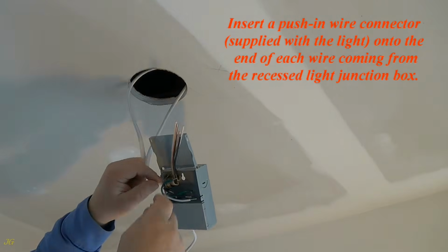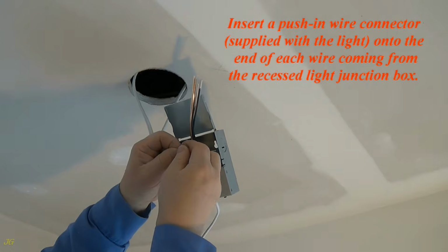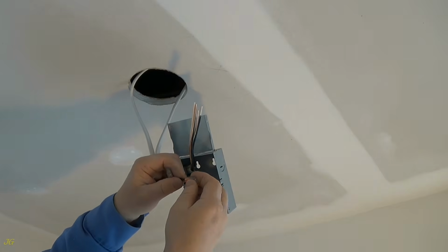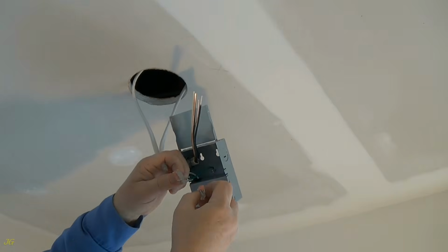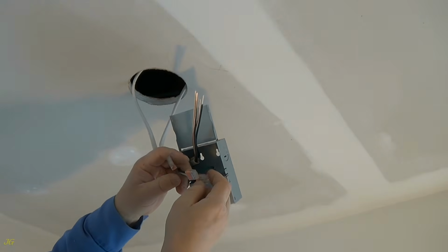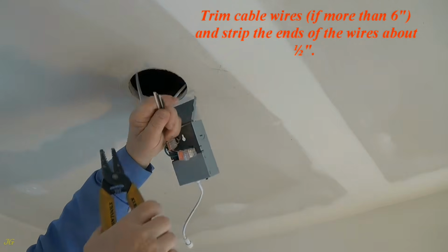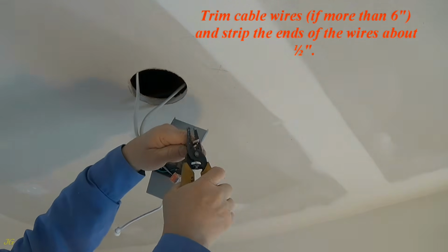Insert a push-in wire connector, supplied with the light, onto the end of each wire coming from the recessed light junction box. Trim cable wires, if more than 6 inches, and strip the ends of the wires about 1/2 inch.